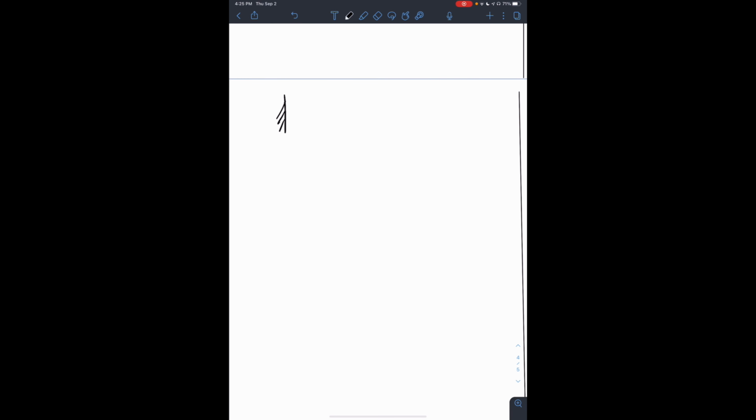If we have a beam and the beam is bending, so let's exaggerate how the beam is bending here, right? Because we have some force over here. In order for the beam to bend and curve, in order to get that curvature, it means that this distance from here to here, S top, I should say, because it's the top, is actually greater than this curved distance here, S bottom.